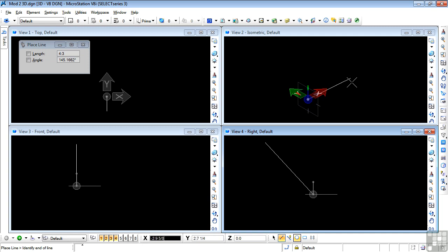Now, the next very important thing is that we need to orientate the compass, which at the moment, as you can see in the isometric view, is looking vertical. The important point to note here is that the compass is vital to your drawing technique, since you're always drawing in the plane of the compass. And this is now a 3D plane, so you need to be able to move the plane around in order to draw within it. Now, in our case, we need to change this.